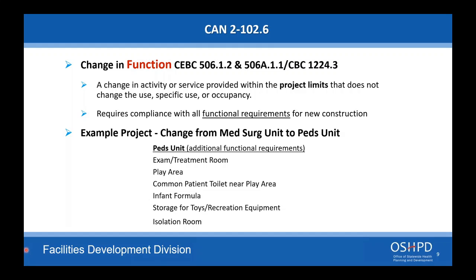If you're switching from a med-surg unit, remodeling it to a pediatric unit, the pediatric unit has additional functional requirements. It requires an exam and treatment room, a play area, a common patient toilet near the play area, infant formula, storage for toys and recreational equipment, and an isolation room.